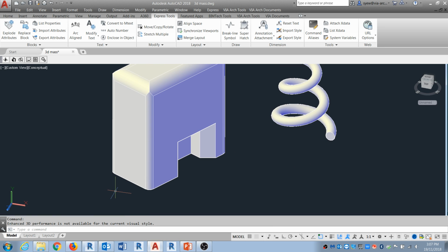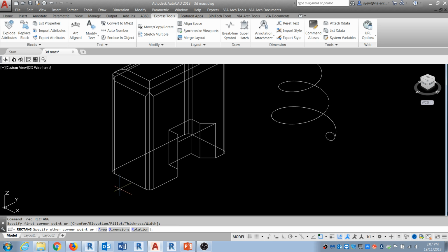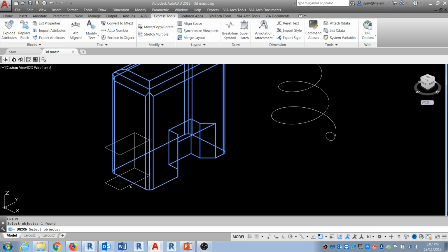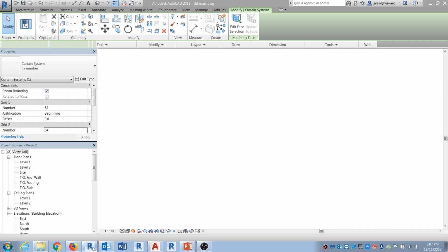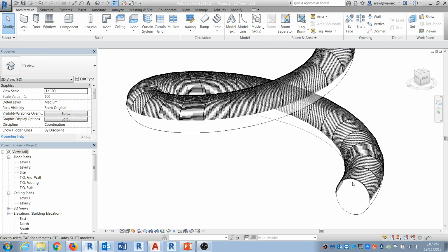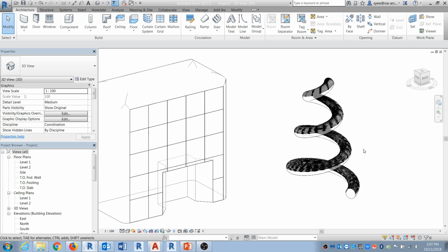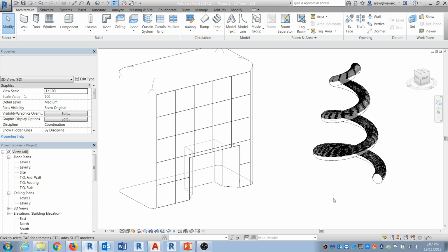I forgot to mention there are a couple of other tools you could use. Let's assume that you want to create something. I'm going to go UCS back to normal. Okay, so here what you can do is that if you want to add stuff, let's assume that this is what you want to add. You can use the command called UNI, Union. What it does is it basically merges this with that, and it will turn that into one complete object. So when you click on this, it's one complete object. Oh yeah, there we go. That's very sexy. So you can create a bunch of snake-like profiles.